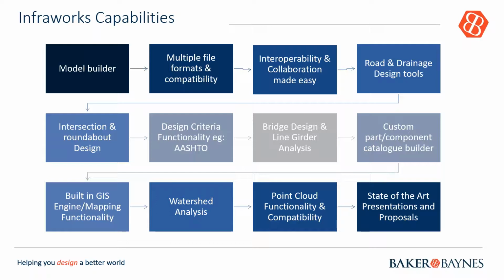It's compatible with multiple file formats. Like I said, you can bring in shape, STF, those are GIS. You can link in Revit, Inventor, parametric models, you name it. We've done some really wide scale designs on this, and it works really nicely. Interoperability, more or less related to the same thing. You can do road design, intersection alternatives, roundabouts. It's got AASHTO criteria built in. LRFD, that's for bridges, all of those type of things, all built in. Point clouds, you can import them in, create watershed analysis. The list goes on, but these are just some of them that actually stand out.